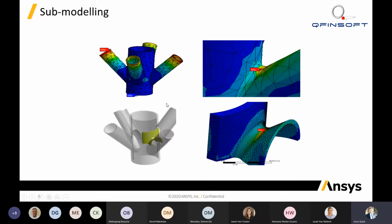Over here, we can see, just for an example, what the submodeling involves. We take our global coarse model and do our analysis on this model. We identify, for example, a high stress region, as you can see at the top right, and then we decide we'd like to investigate that region further. So we go back into geometry, cut it out, and then refine our model within that region. Submodeling can be a little bit tricky sometimes, but that's why you have us to give you support in fixing up your models, addressing some of the limitations, and so on.